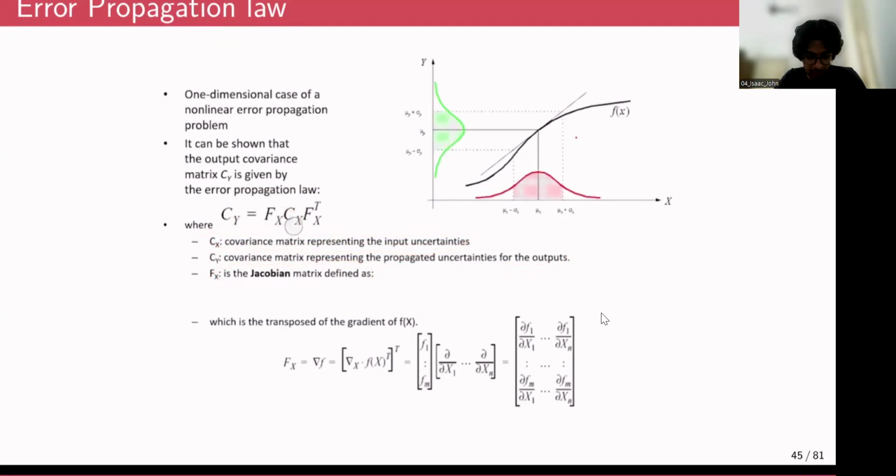And this error covariance matrix, you can actually model it on your own based on some distribution, right? No one can really tell how these errors are distributed, but you can have some sort of an estimate through a lot of experiments using these sensors.